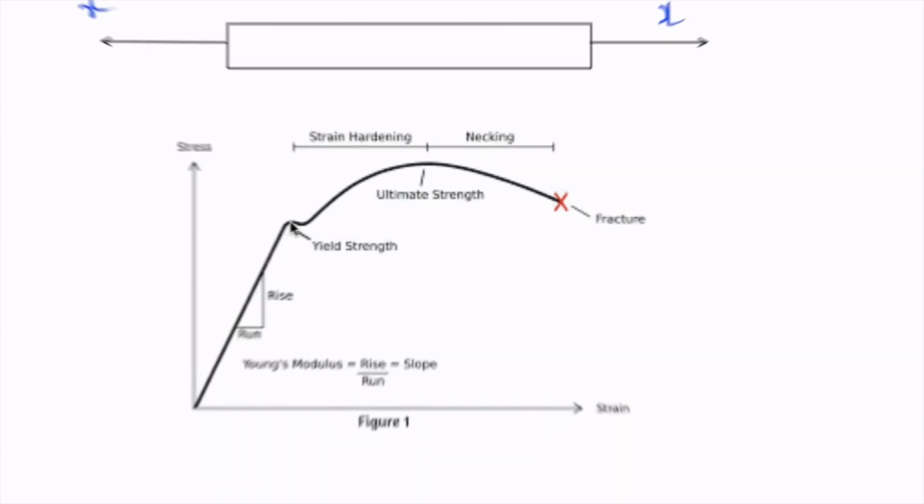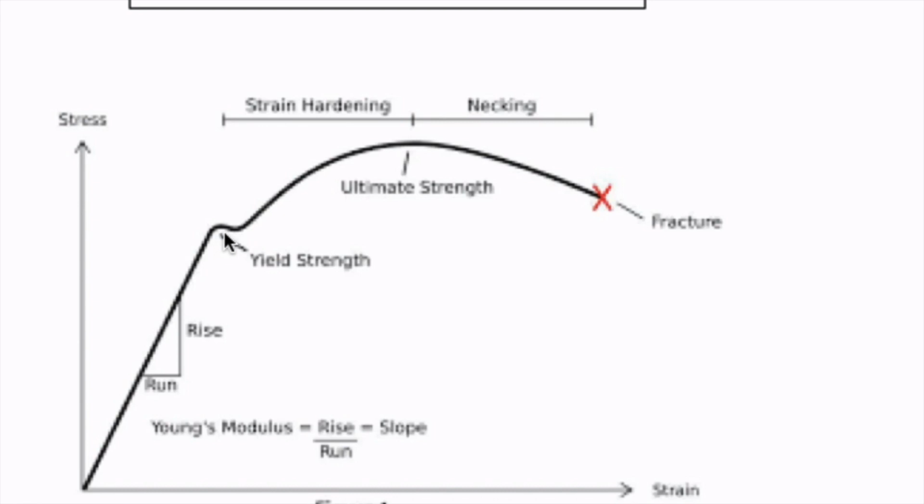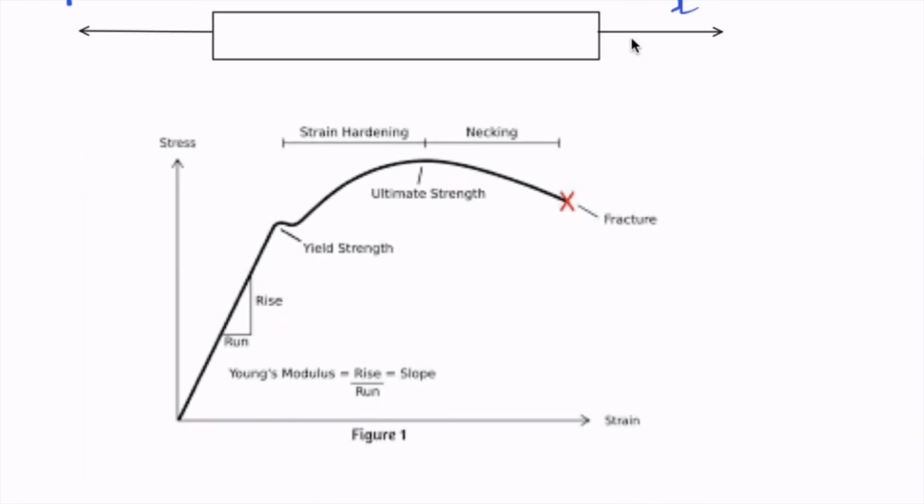at the point of yielding. So in case of static loading, you give a load that does not change its direction or magnitude continuously with respect to time. In this kind of situation, yield strength has a very important role. Yield strength is a limiting factor of this material, because at the point of yield, the material starts to deform plastically.